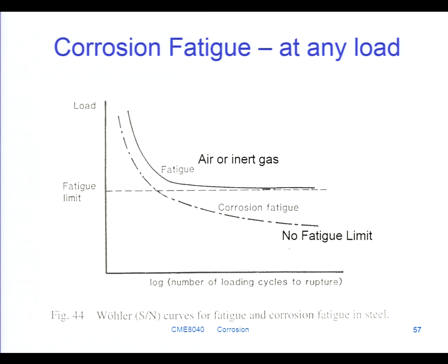So you've got a residual stress that may be as large as approaching the yield strength, and then you've got an applied stress on top, whatever that mechanical loading is. When you get corrosion fatigue, when you're actually exposed to a mildly corrosive environment, then your fatigue limit disappears, which means all your design factors, all the guys sitting in the office with the finite element analysis might as well go home. Okay. They don't have the solution, because you can't really model this, you have to test for it. And the bad news is that you have to test for it.